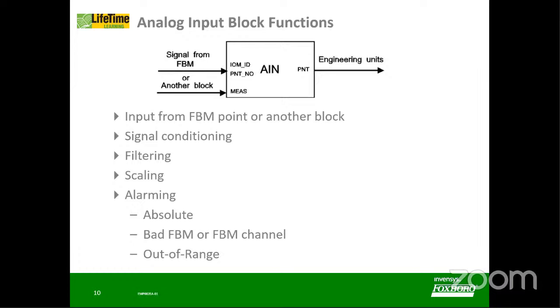So in those cases, you can define in the alarming set points that I need to receive the value from 4 to 20 milliampere, and in any case, if the value is received below 4 milliampere, I need to have an alarming signal on my analog input block. With this, whatever alarm comes from this analog input block will be displayed on an operator screen. So the operator will immediately understand that this particular analog transmitter is now malfunctioning, or it is not giving the appropriate output value.